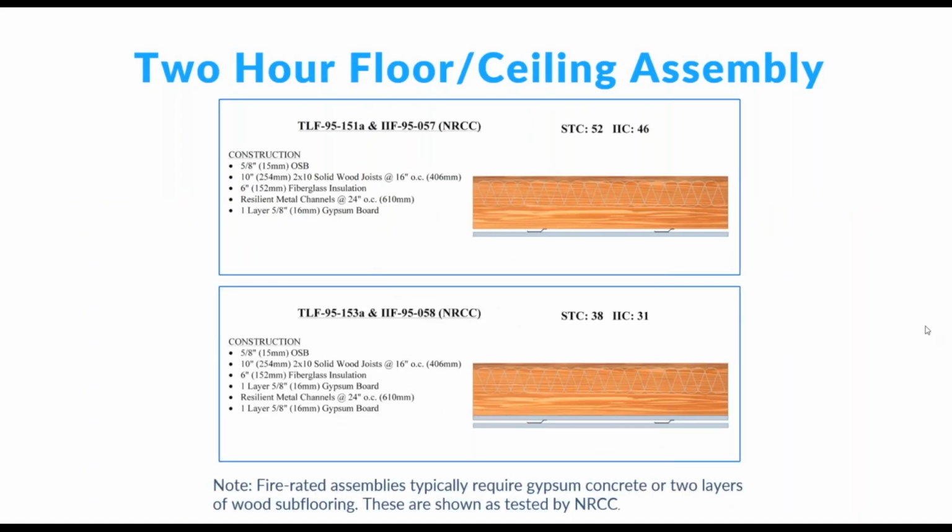So I'll show you some test data from the National Research Council in Canada. At the top, we have a very basic floor ceiling assembly, one we've been looking at already. And this tested at an STC 52 and IIC 46, with resilient channel and some insulation in the cavity. And if you've been paying attention, you'll know that this assembly probably wouldn't meet a UL design, wouldn't be a fire rated design because of the RC spacing and insulation thickness.